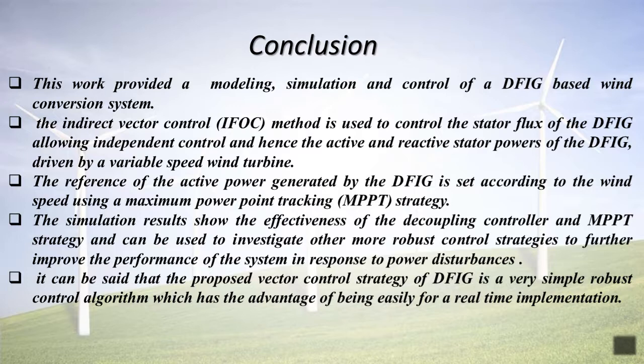The simulation results show the effectiveness of the decoupling controller and the MPPT strategy and can be used to investigate other more robust control strategies to improve the performance of the system in response to power disturbances.